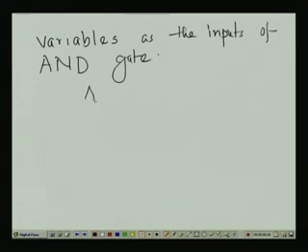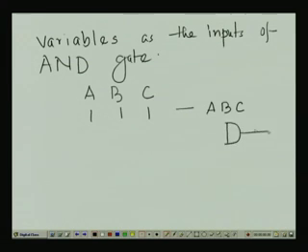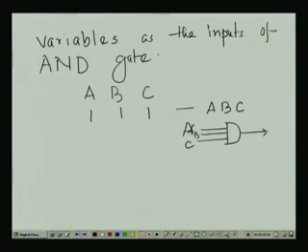That means, if A, B, C in one row are all 1, it gives the product term ABC, which is actually a 3 input AND gate. So mainly the AND arrays, on the left hand side, represent how we can take the different AND combinations.